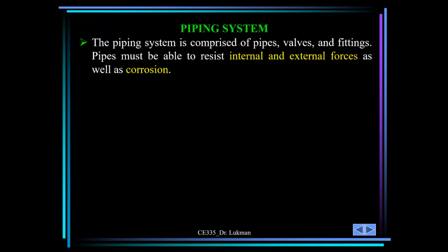So that is why the internal surface area of the pipe is usually coated, because pipes are sometimes made of steel. Steel is susceptible to corrosion depending on the quality. So you usually have it lined with non-corrosive material.